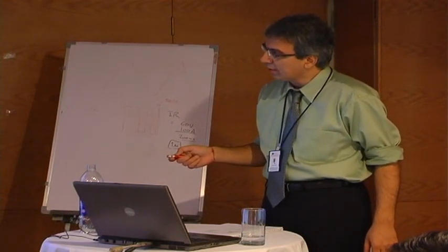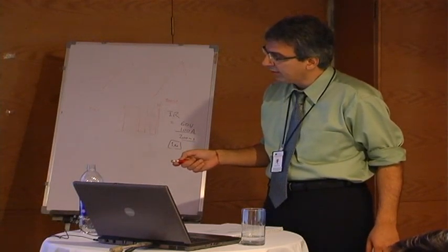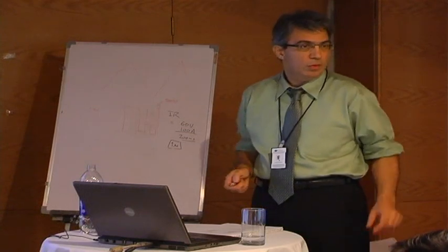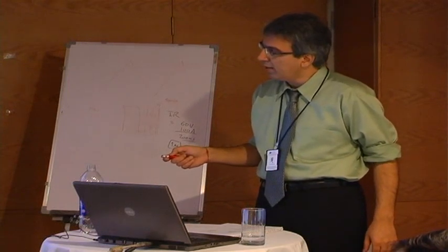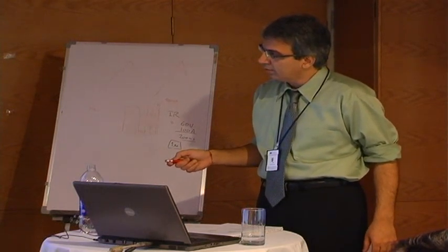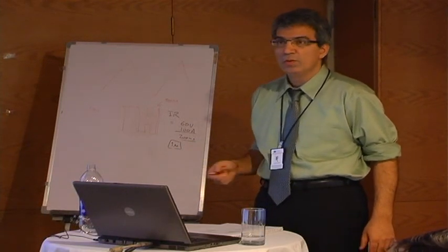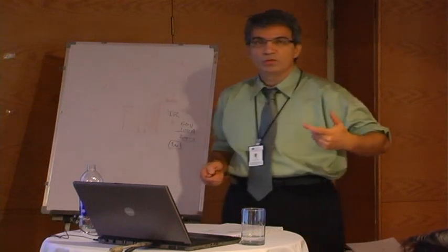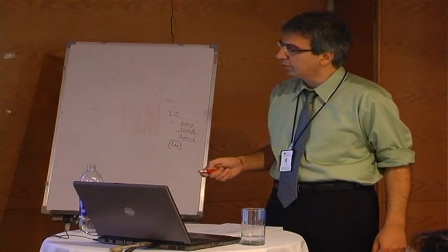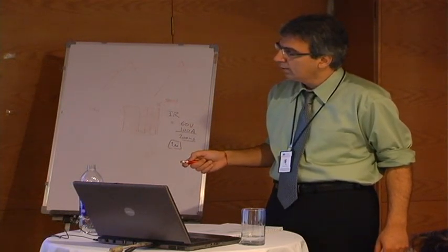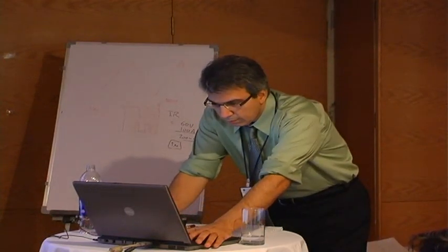Now there's a gain G here that defines the roundness of these pulses. If you make G higher, these become more square, and if you lower G, these become round. So if you're running into convergence issues, you can use this G number to smooth out some of the convergence issues. Let me just show you the Excel sheet.